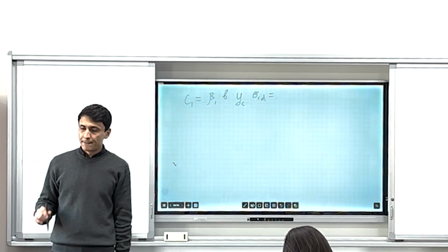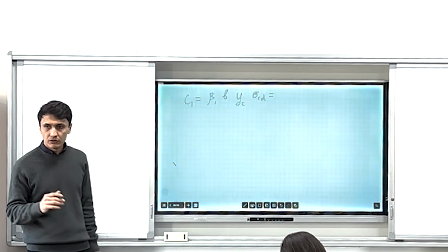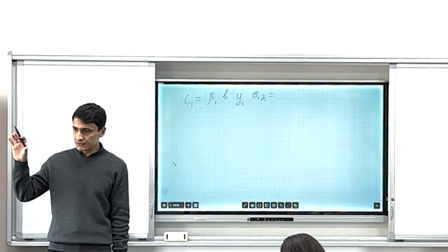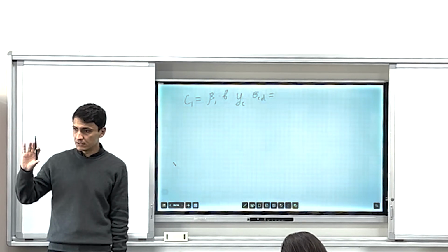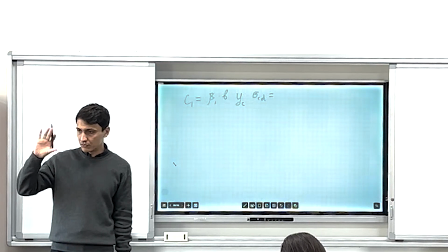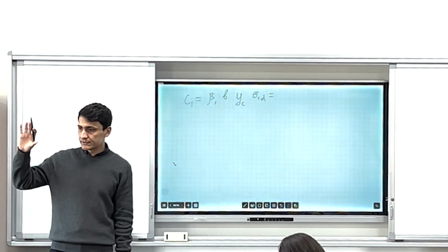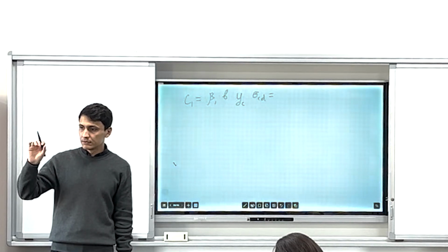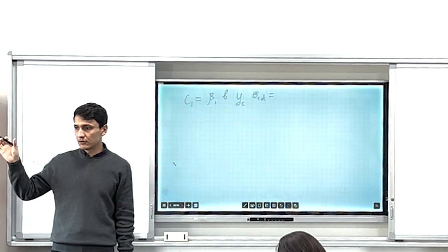Why? Because if you don't know YC, you cannot solve the equation. You cannot find the bending moments and the forces coming from rebars and the concrete. If you know YC, you can find the forces. Then at the end, you will sum them up and check whether it is correct or not.